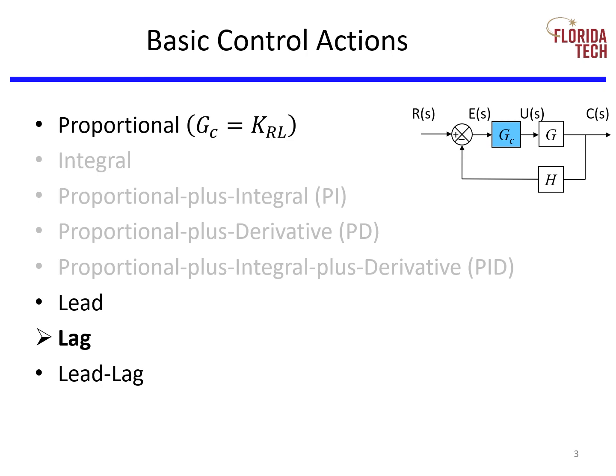In the last section, we covered lead controller design. Lead controllers have the same effect as PD controllers. We saw that lead controllers quicken the response of the system, which is generally desirable, but can worsen steady-state error of the system, which is not desirable. Lag controllers have the same effect as PI controllers. They improve steady-state error, but can slow down the system response.